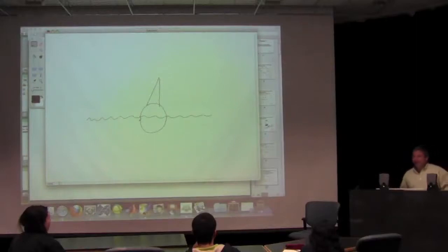There are lots of different ways you can make thermometers, but the most common is something called a thermocouple. It's two wires of dissimilar metals that are joined together, and when you join two dissimilar metals together, they form a potential across there. If you change the temperature of the weld, you can change the resistance across that weld, and it's proportional to temperature. So it's a very simple device. Get a copper wire and a Constantan wire, weld them together, and you have a temperature measurement. That's all it takes. Let's say I put that thermocouple right here.